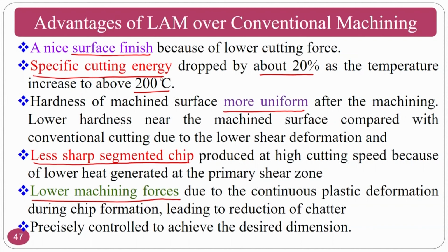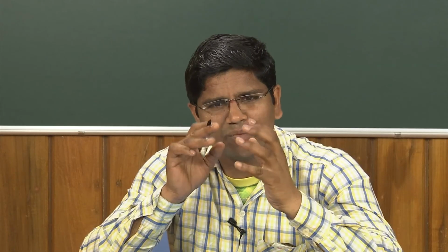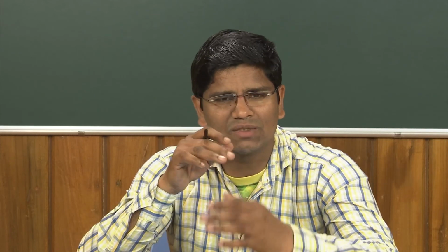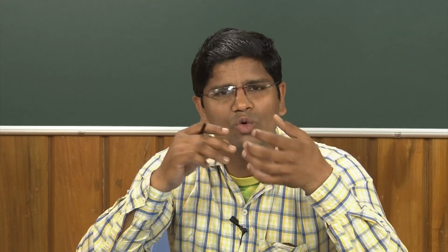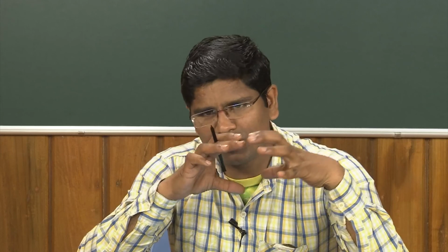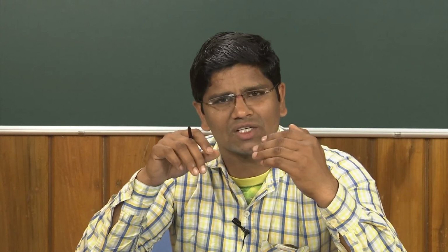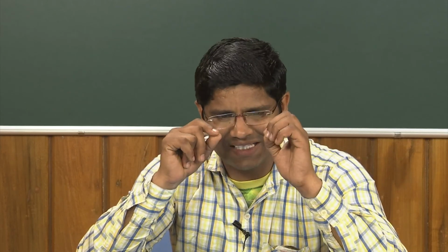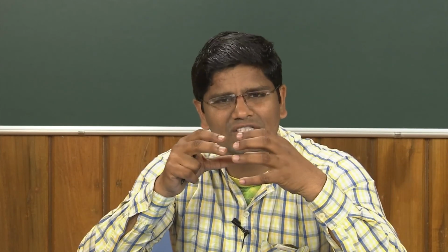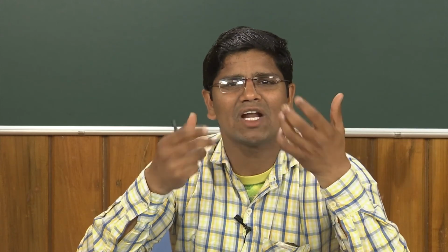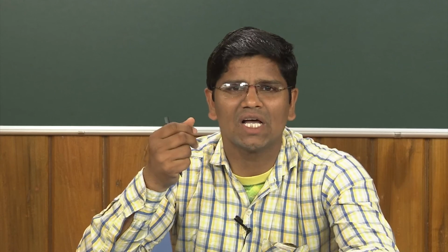Not only the laser, but people who want to do hot machining of ceramics can go for an oxyacetylene flame also, because purchasing a laser may be costly. Those people who want to do research in this area, what you need is a welding torch, that is, an oxyacetylene flame. You just take the workpiece and arrange your oxyacetylene flame in such a way that it will machine it. It may not be exactly localized, it may be slightly diversified, but still okay. The only thing you need is to do that at an economic price. Okay, you can do a very good thesis in this way.